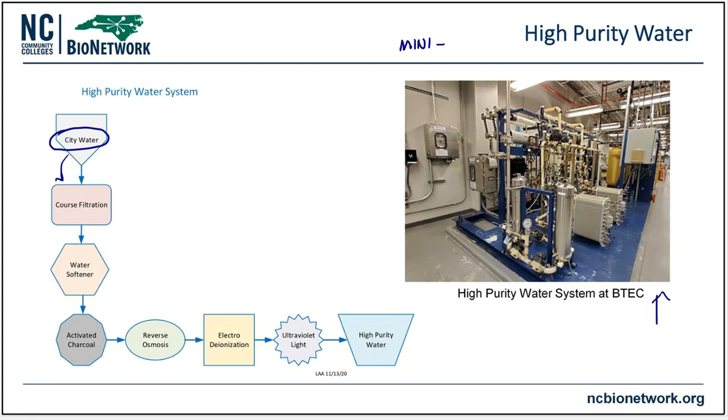That's still a contamination problem. After it filters, then it can go through a water softener. We talked about this as well, and that will remove any calcium or any magnesium that might be built up, which are very common cations that carry positive charges in a water sample.